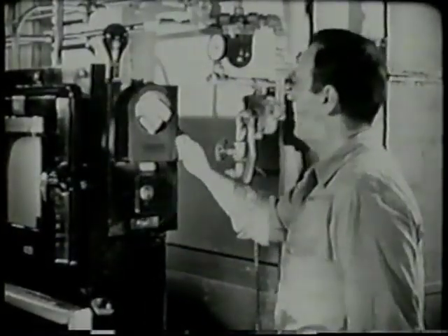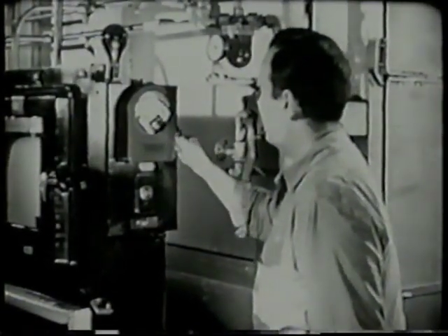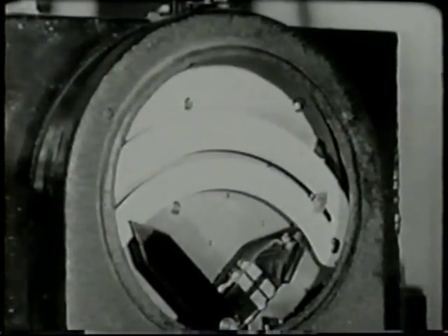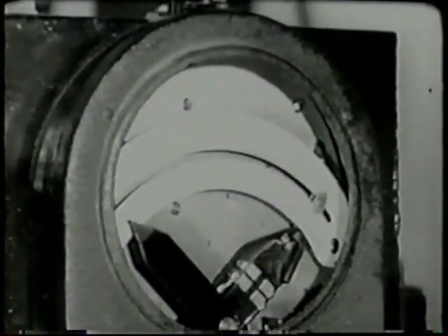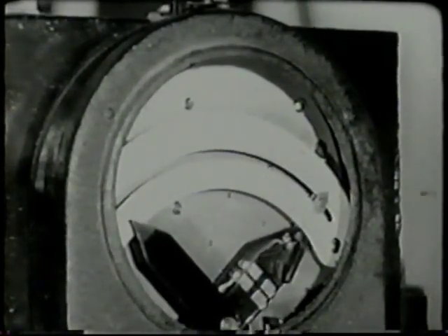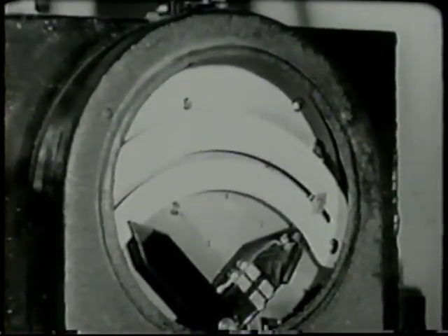The automatic timer is set to cover the proper heating time or soaking period. This will vary with the thickness of the alloy and its composition. For example, an alloy 24S part 1/8 to 1/4 inch thick should be kept at heat treating temperature for a minimum of 60 minutes in an air furnace.